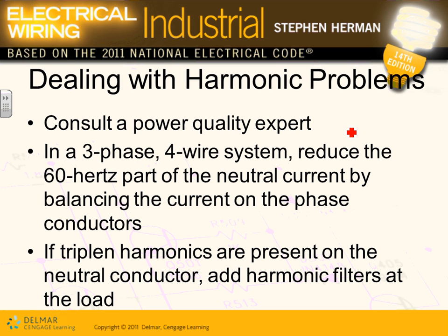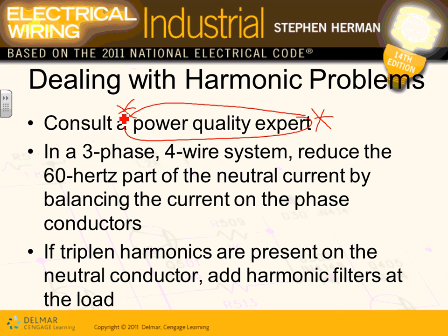Dealing with harmonics. So how do you deal with harmonic? Again, quality experts. A lot of people, guys, I can't emphasize this enough, in this day and age, when we deal with harmonic, we have a quality multimeter. If you have a multimeter, guys, it will give you a report about the kW, the amp, the voltage, the frequency, everything in your building, plus the harmonics. Which harmonic and what size. So it's a big deal.